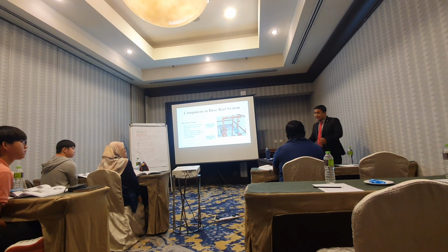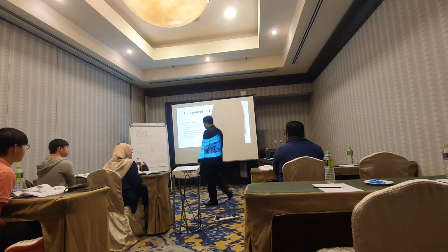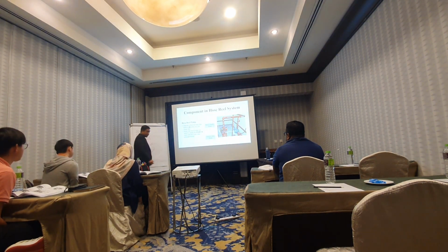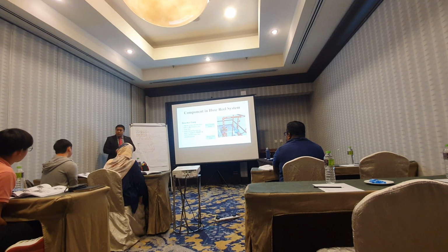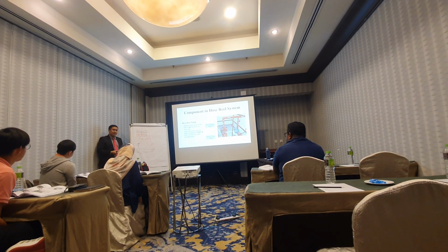If you are asked to design a godown ataupun gudang, a storage place, you might have more hose reels when you put the fire safety objective as life safety and property protection. If it is for property protection, you can have more hose reels. Sebab apa? Dekat gudang, it is an open space. You can have more people to operate more hose reels in one fire.